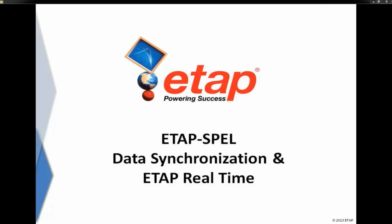The first one is the analysis and validation of the retrieved data published from SmartPlant Electrical into ETAP, and performing a basic load flow study in ETAP to make sure the equipment is sized properly. And then we will demonstrate the operation, monitoring, and prediction piece by taking the ETAP project to real-time online mode and monitor the system behavior under different conditions, such as losing a generator, and monitor shedding some loads and see how the system reacts.